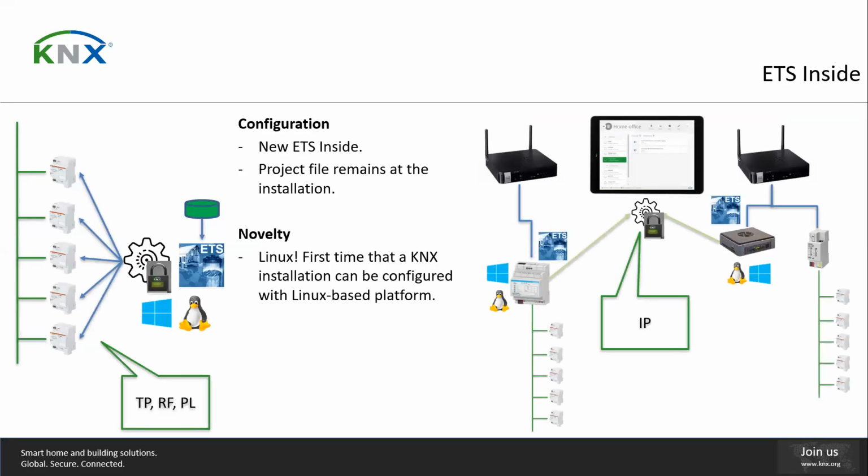As for the ETS Inside, being one of the latest novelties in KNX, I mentioned there is one unique tool to configure all the KNX equipment. This is normally a tool that is owned by the system integrator. In pursuing a bigger market, especially smart homes, KNX Association released a couple of years ago the ETS Inside, which basically is a simplified ETS software that allows a more simplistic design and commissioning of the installation. So you can use, for instance, a tablet or a smartphone to configure a KNX installation.